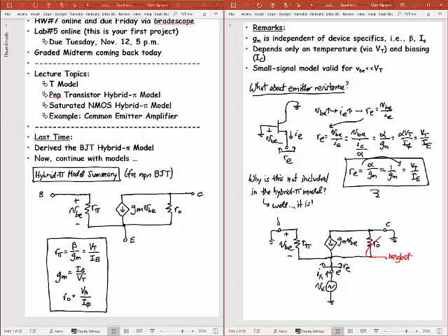We sort of did this last time, but if you want to think of the resistance seen looking up into the emitter here, how do you get that? You say, well, if I got a voltage VBE across this, that's the resistance. So I put a test voltage down here, and it would drop a voltage VBE across this, which would then source a current.